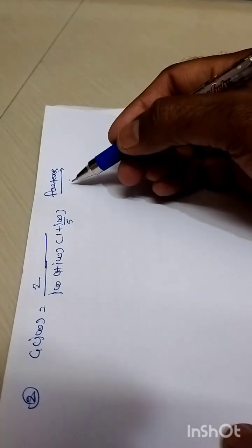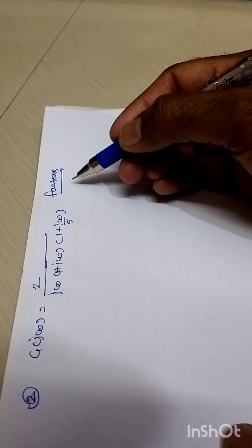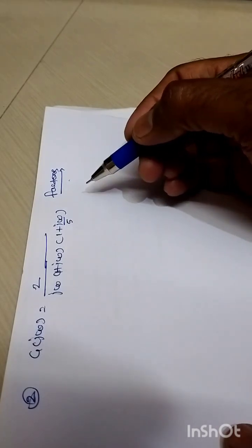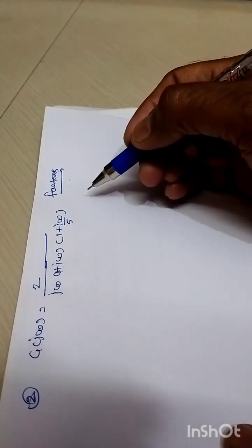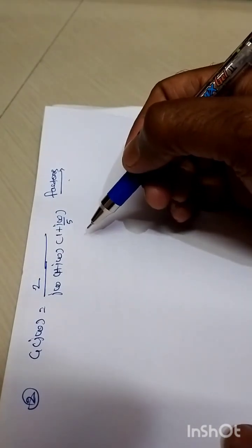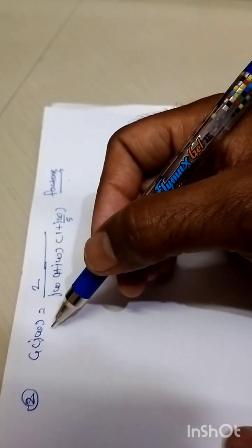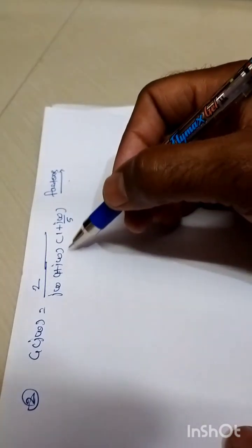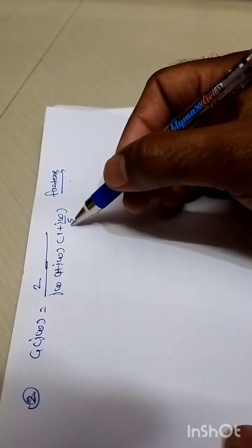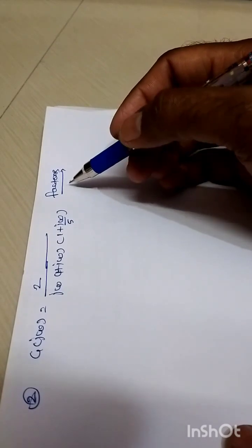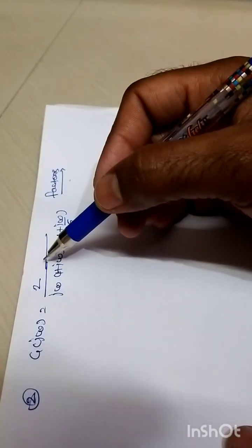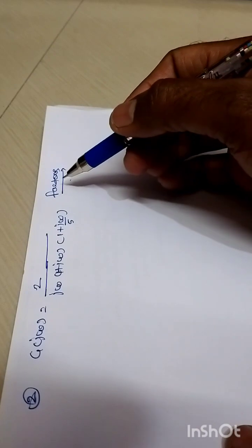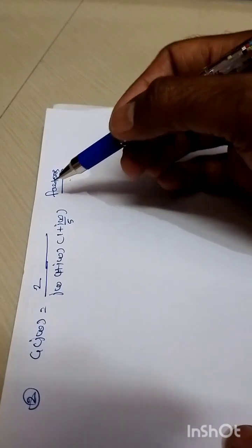So factor in the sense how many constants we are having, how many zeros and how many poles we are having, right? As far as zeros and poles are concerned, these are the two desired frequencies of this transfer function, which are to be determined when we equate the denominator polynomial equals to 0. This will give you the number of poles, and when we equate the numerator polynomial equals to 0, this will give you the number of zeros, right?